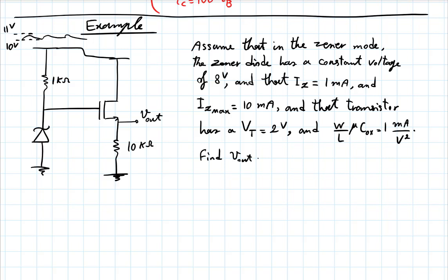For a moment, let's think about the fact that the MOSFET in DC steady state does not draw current into its gate, right? The gate current in DC steady state is 0 for the MOSFET. Now, is this problem in DC steady state? No, because the input voltage is varying. Now, the variations, you might say, are small, between 10 and 11 volts. So that does not represent a very high AC signal. It's almost a DC steady state plus some ripple on top of it.